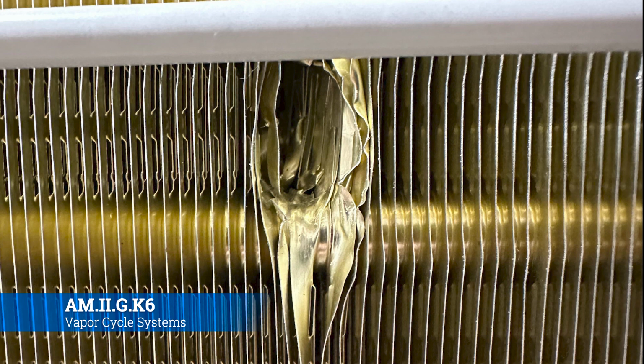Okay, condensers are kind of a weak link in the world of AC systems. So these coil fins are there to help radiate that heat and return the expanded refrigerant back to being a liquid. Now the problem with this is that they have to be so thin in order to effectively radiate it that they're also extremely susceptible to damage. This is really easy to see. You just go check your HVAC system at your house and look and see anytime that anything so much as barely touched it, it'll bend it.